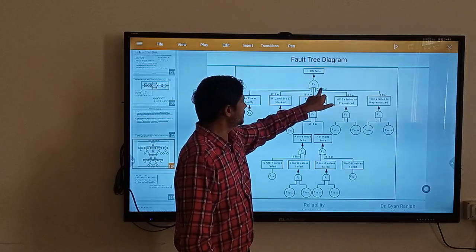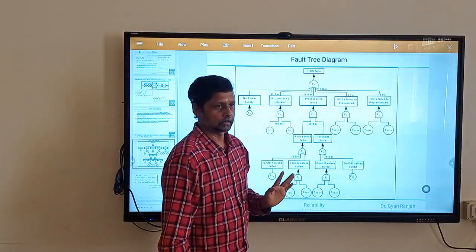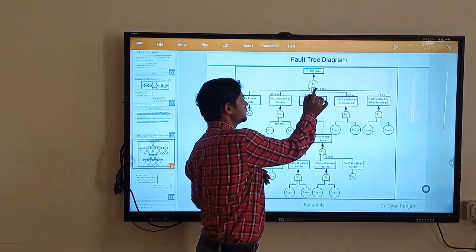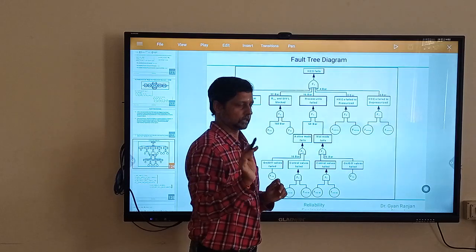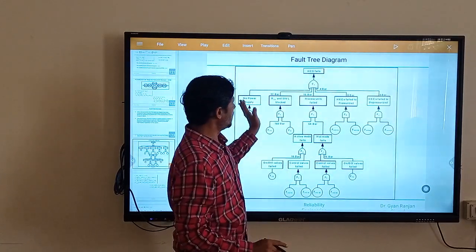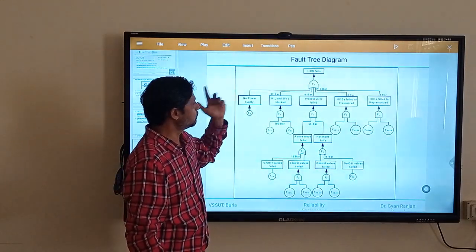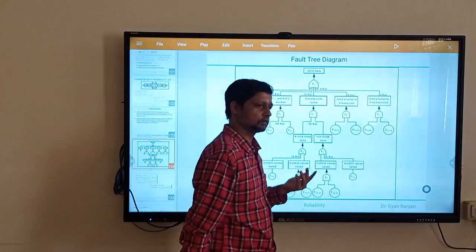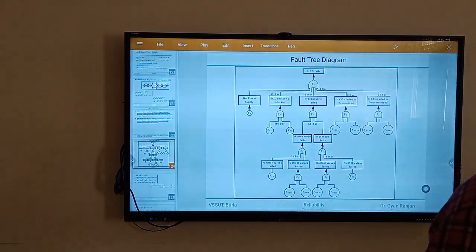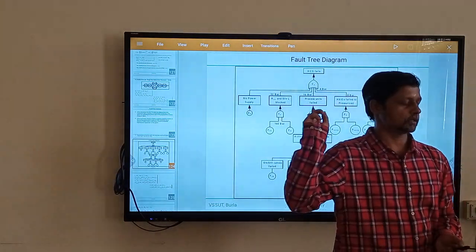Now this 4 bar indicates that you have to feed it at 4 bar pressure. Okay? I have nothing to do with what you are doing inside. You constantly supply at 4 bar, immaterial from wherever you are. Now my whole P&ID is taking care that number one probability could be power supply. Power supply failure is possible, so I need to take care of that.